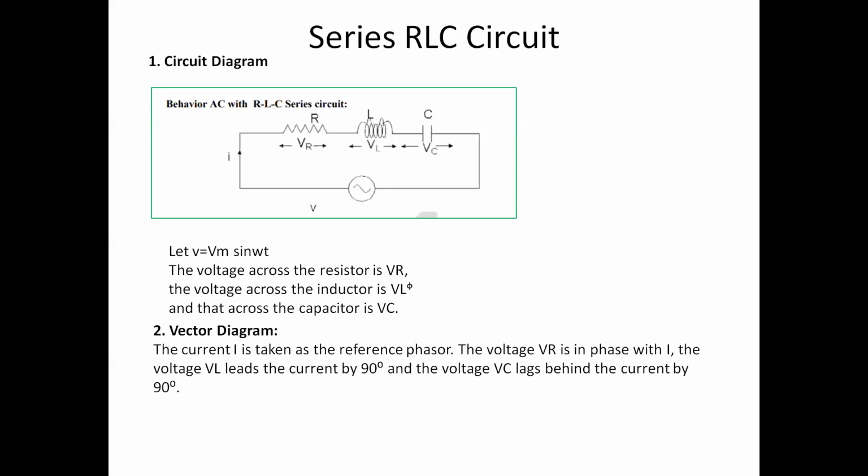All right. So that being the application, now let's look at the working. RLC elements are connected in series. A sinusoidal voltage source V is connected across the three. Capital V represents RMS value of supply voltage, and terminal voltage VR represents resistive drop. VL represents inductive drop across L, and VC represents capacitive drop across C. All right, and the vector diagram.